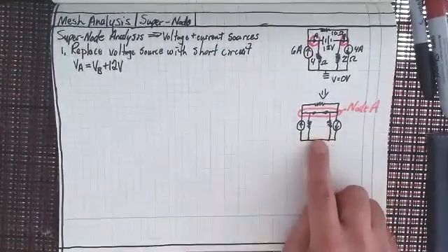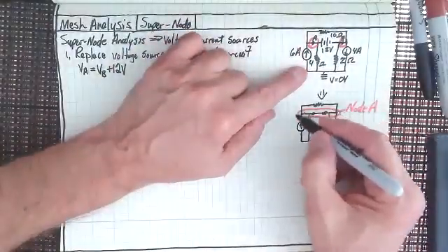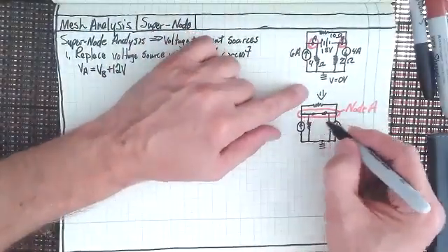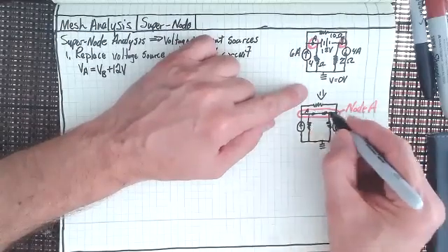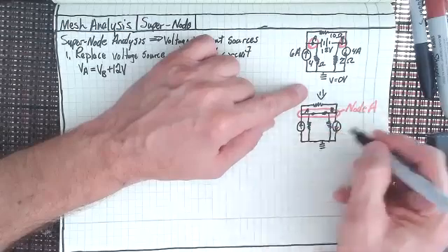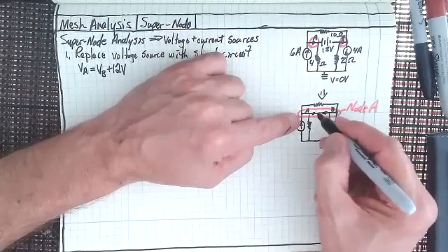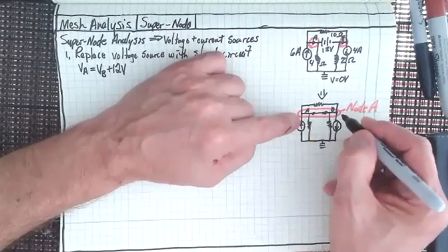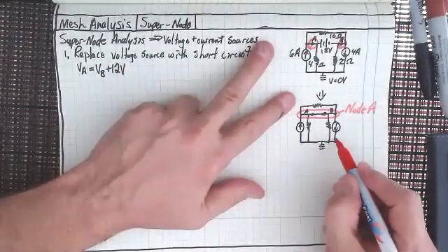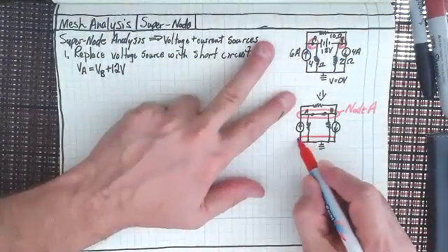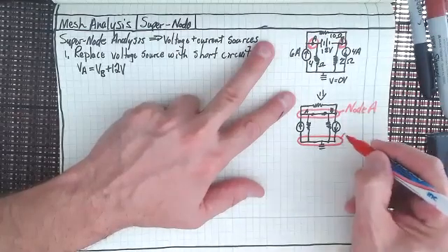Now, that's not for this circuit, though, because in this circuit, we see that the first thing that we're going to do is we're going to make node A contiguous, aren't we? So now voltage at A and voltage at B underneath this supernode analysis is going to create one node with one voltage. Where would our other node be? Well, I think everybody can see that we've got another node down here, don't we? So we have two nodes.